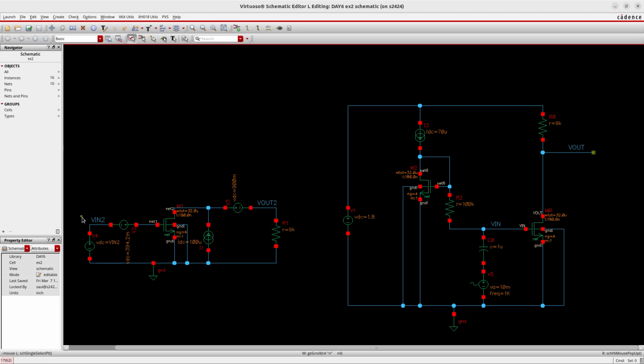If we don't do it this way, we will have to rely on a circuit that is almost finished, a circuit in which the biasing has already been implemented. That happens pretty much later during the design cycle. And if it doesn't meet the specifications, then all the effort that we spent during biasing will be basically in vain, because we will have to do it again after we fix the nonlinearity problems. So that is a very important aspect of trying to extract as much nonlinearity information as possible very early in the design, namely when we have just self-biased transistors.